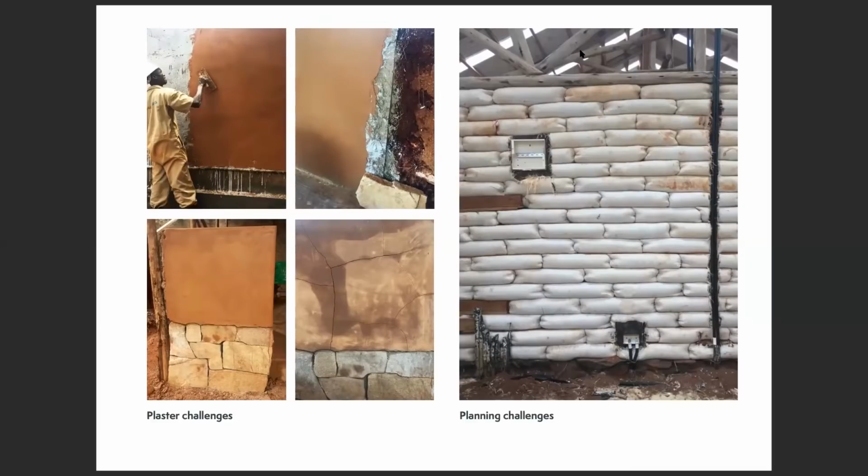But this is not only because of the embodied energy, as Edson has mentioned; it is also about the nature of the plaster. We want something that is vapor open, something that allows any moisture to move freely through the wall. The moment there is moisture trapped in a wall, the structural stability suffers. Edson, do you want to share with us a little about the experience so far? We are still halfway through, but the experience so far with earth lime plaster.